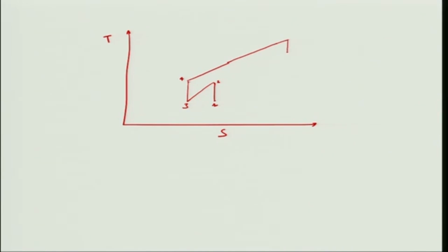Here we try to reheat, okay, and then we have this connector here, and then of course we can make use of the fact that these temperatures are higher than the exit temperature of the compressor, and thus we can also use regeneration.